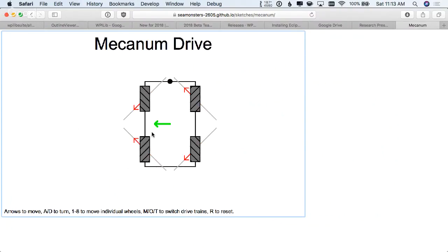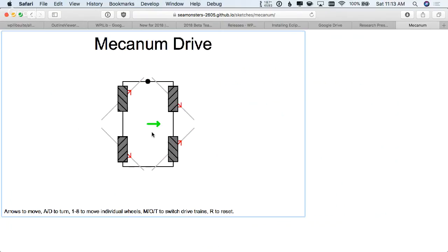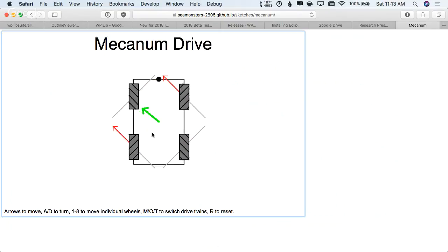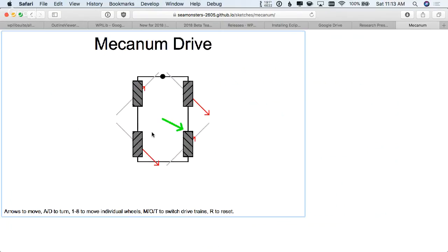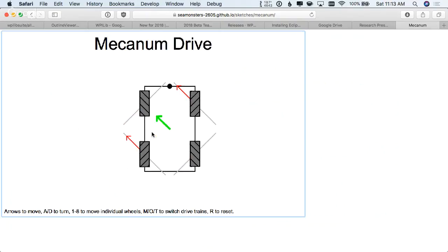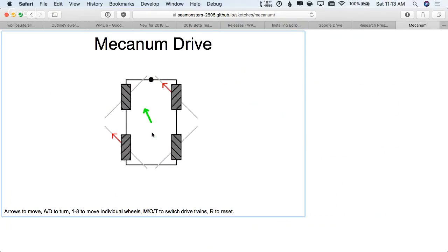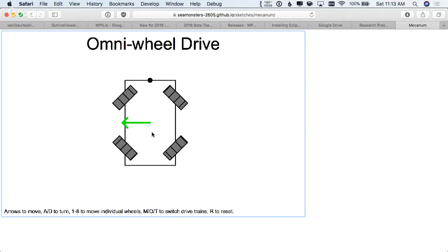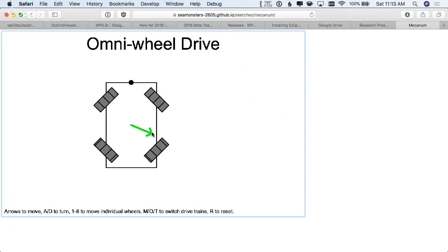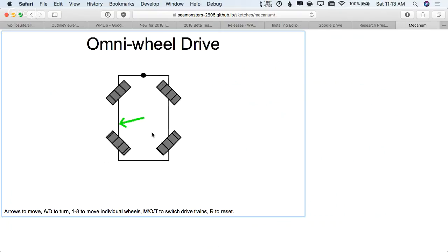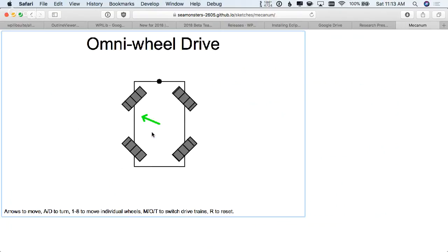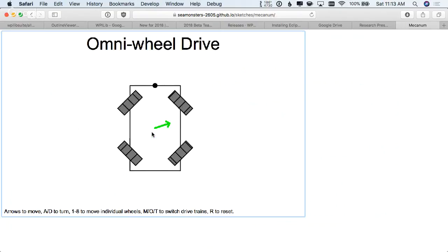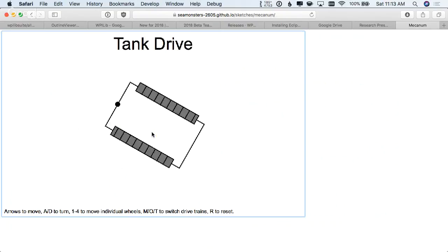Okay, and try that with wheels. You know, and so it's very, very maneuverable. And so they use it for forklifts in tight spaces, because the forklift operator goes down an aisle, grabs the stuff, just backs up a little bit, and then just goes this way. Because they can't make the turn, because the thing they pulled out, like the lumber, is wider than the aisle, and it can't make the turn. So they just go out sideways.